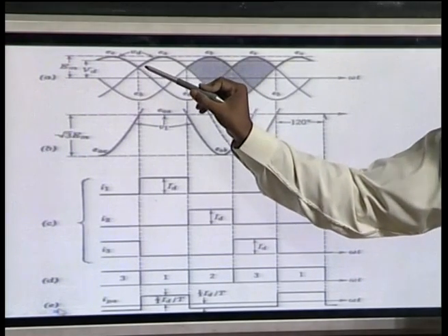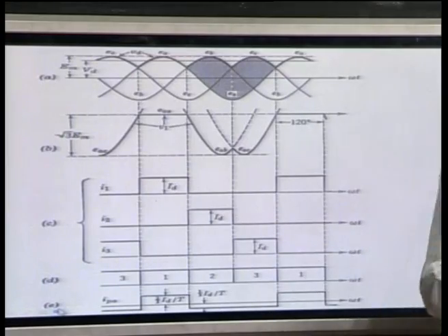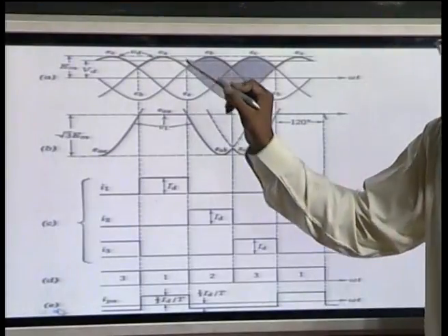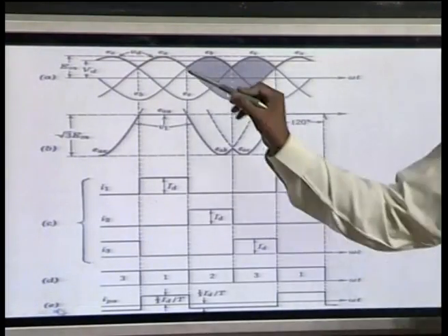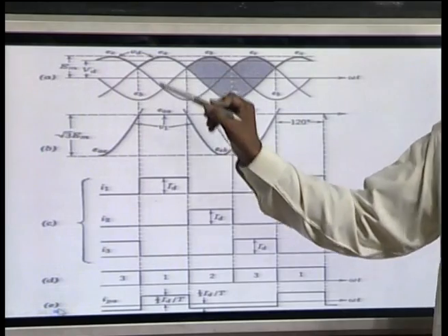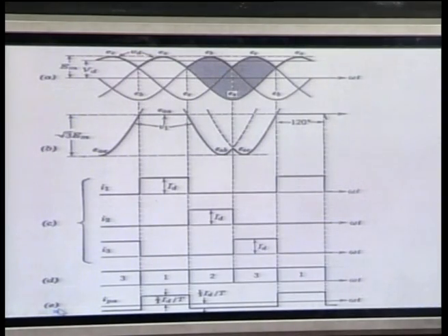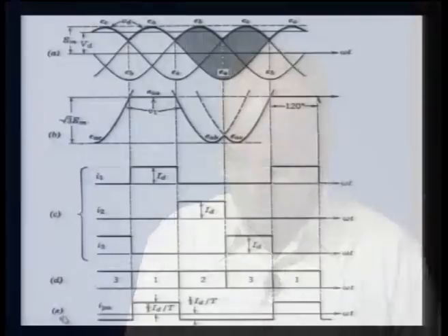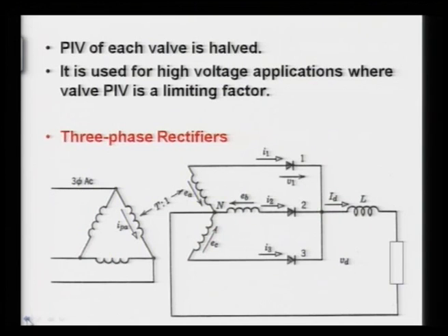So, what happens here? As said, we are assuming there is no delay right now. We are assuming it is a perfect diode. So here it can ignite, your valve 1 can be conducting, and once 1 is conducting, your output voltage becomes EA. I think the previous slide showed the circuit, but once we analyze this wave shape, it will be important that we look at it again.